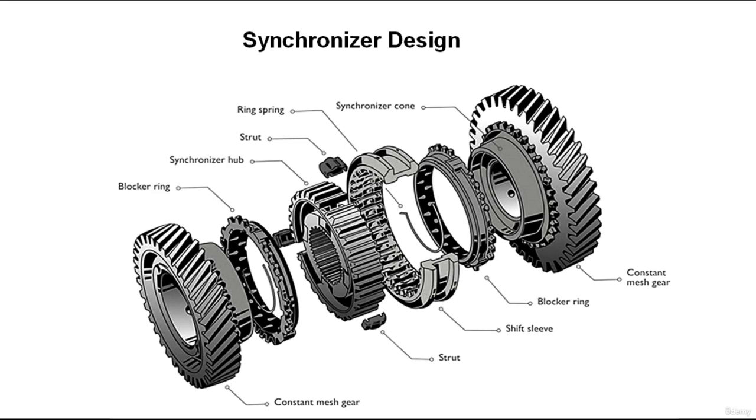Brass, bronze, or powdered iron synchronizing blocking rings are positioned at the front and rear of each synchronizer assembly. Some synchronizer assemblies use additional frictional material on the blocking rings to reduce slippage. Each blocking ring has 3 notches equally spaced to correspond with the 3 insert keys of the hub.